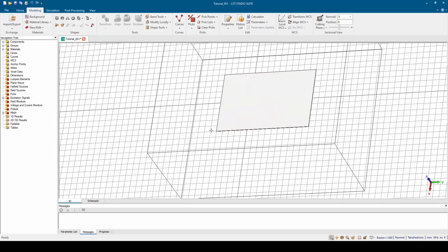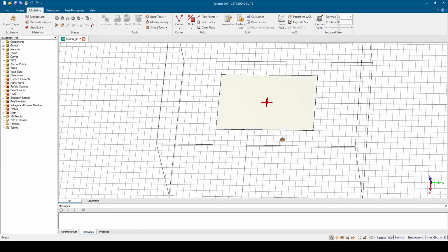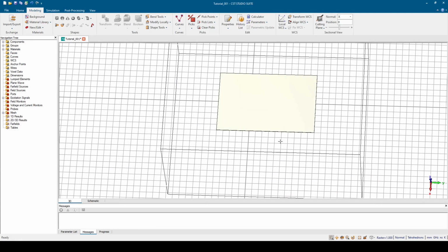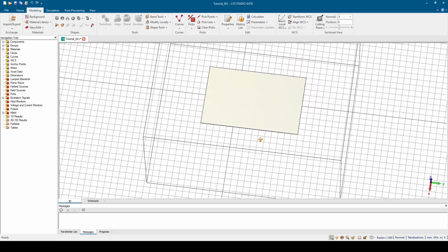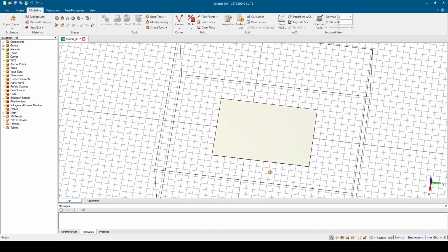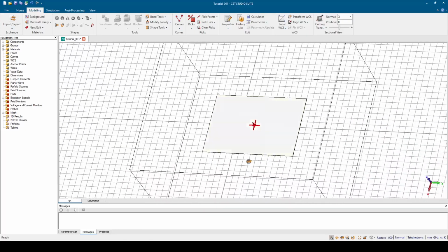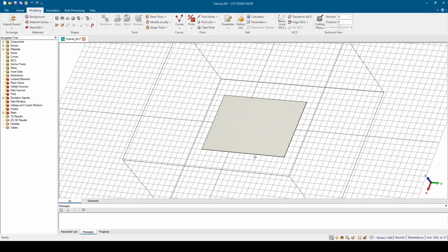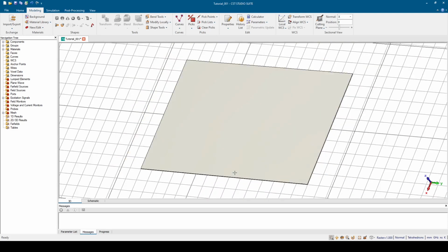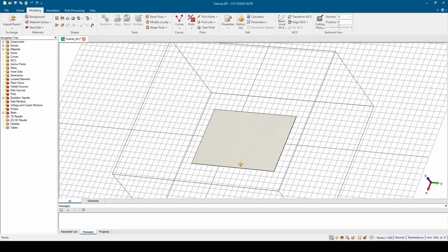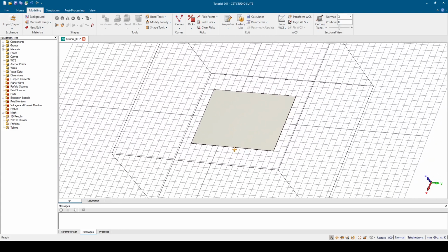Okay, when we press shift and use the mouse, we make the rotations, and if we press control, we move in this way. And when we press both of them and press on the mouse, we move in this way. We can just drag it. So shift and mouse, we can rotate like this, and control we do like this, and pressing shift and control and pressing on the mouse, we can basically move in this way. Okay. And here we scroll by the mouse. Okay. And if we also press on the scrolling and we move, we also do the same thing.